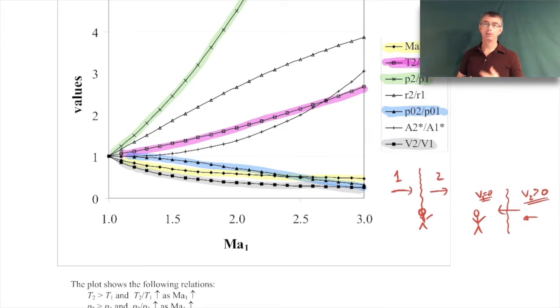Now, I've mentioned in a previous lecture, stagnation pressure is related to how much work you can get out of your gas, right? So the idea is we like to have a large stagnation pressure so that we can do something useful with it, right? But you'll see here that if you have a shock wave, that stagnation pressure decreases across the shock wave. So you can't get as much useful work out of the surrounding gas.